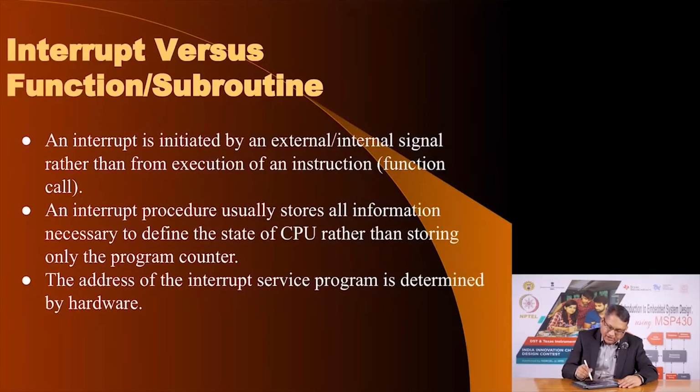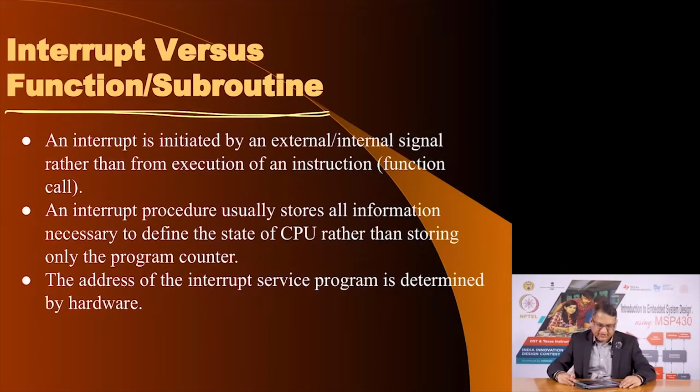It is definitely a little different for various reasons. In a normal function or subroutine, you call that function, right, but in an interrupt you do not call that interrupt subroutine, the interrupt subroutine gets called. Why? Because it is often the result of an asynchronous operation, like a user pressing a switch.